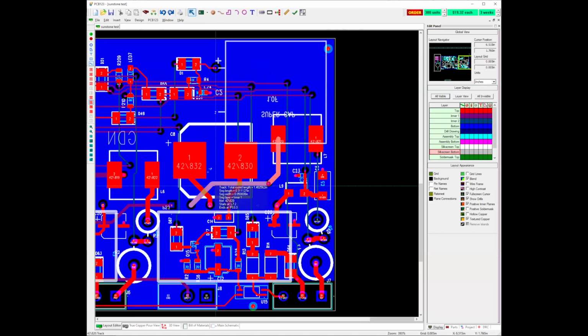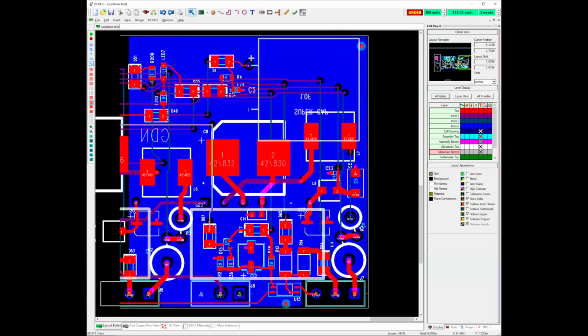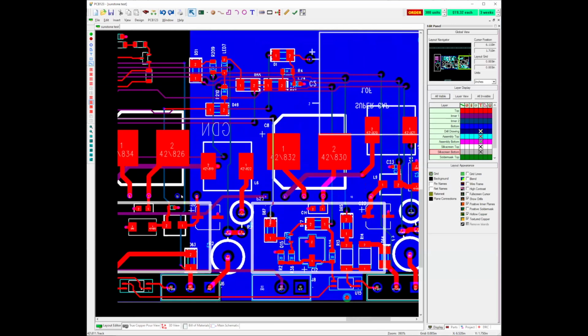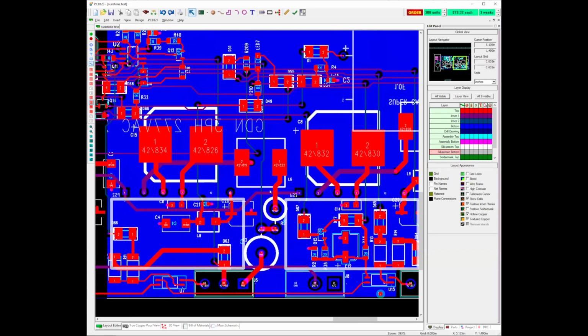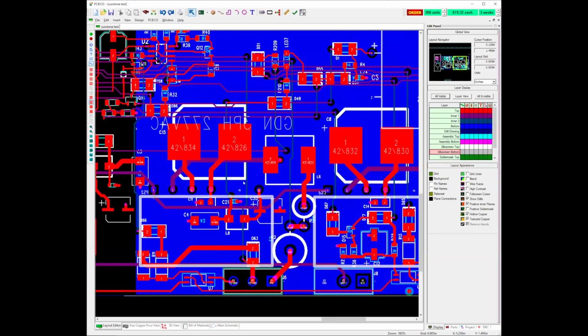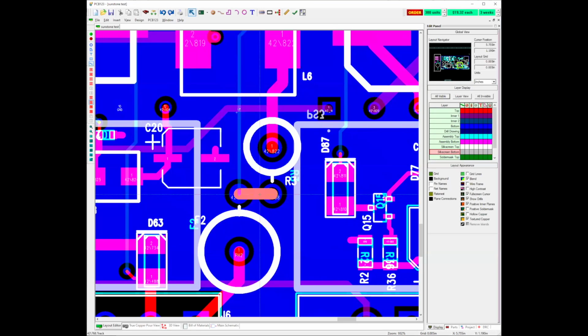It can create a narrow wire that burns out, just flat won't carry the current you're hoping to carry. Like is present here between these two pins. I've got a nice fat wire and a nice skinny one. And this skinny one's just a sense wire, so it doesn't have to carry any current. This is the path here.